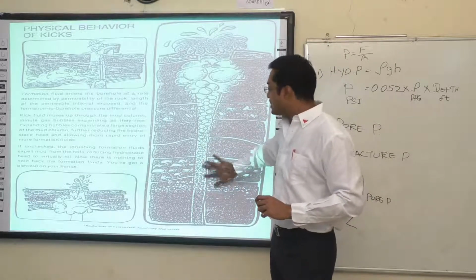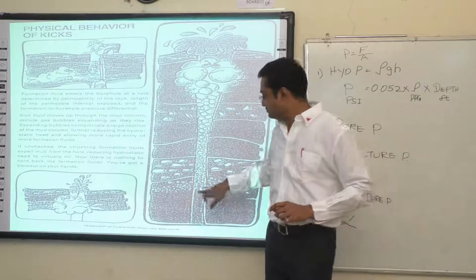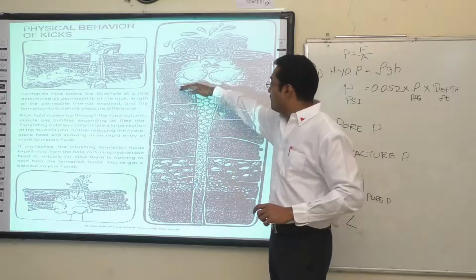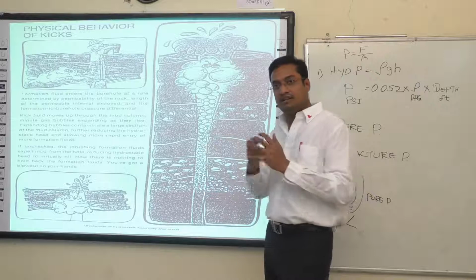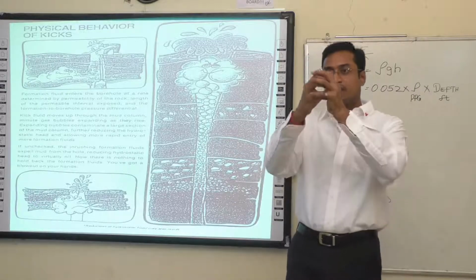When you are allowing the gas to expand, the hydrostatic pressure starts reducing, inviting more influx. When you close the surface, you are not allowing the bubble to expand, so it is going to come up the same way.